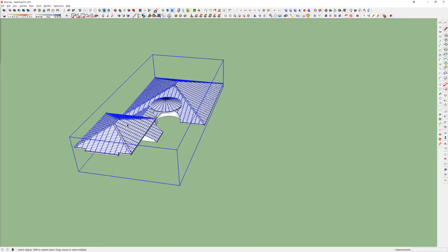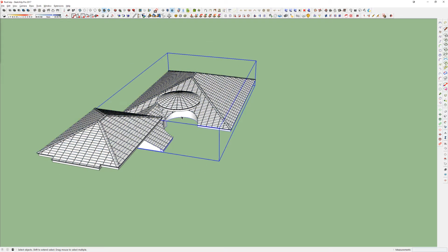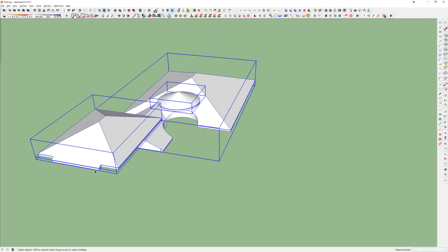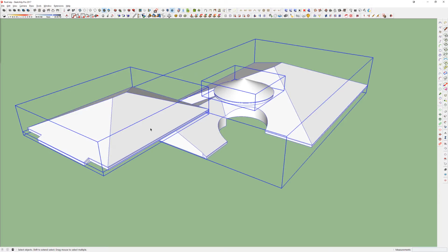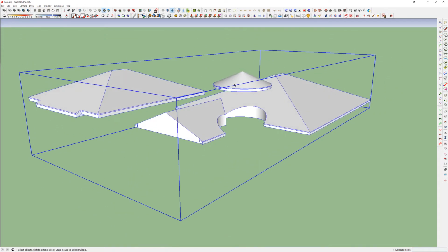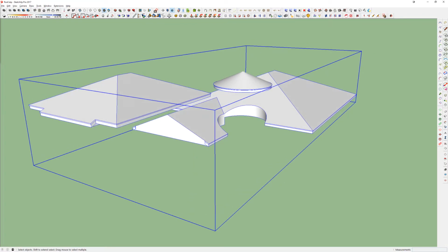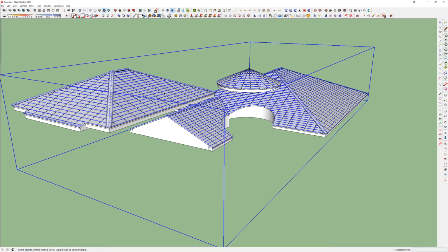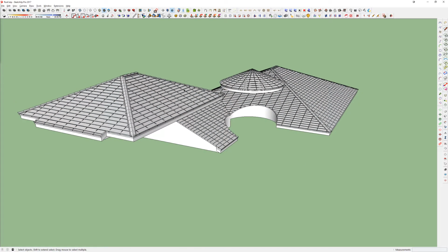So I'm going to put all the roofs on top of each other now, and if you remember the base roof, I'm going to turn my two option roofs off for a second. So this base roof here is just on layer 0. I'm just going to group that all together. So this is just my generic base three-dimensional roof, and then turn my other layers on, and I have essentially material, three-dimensional material sitting on top of it. So from there, I'm done.